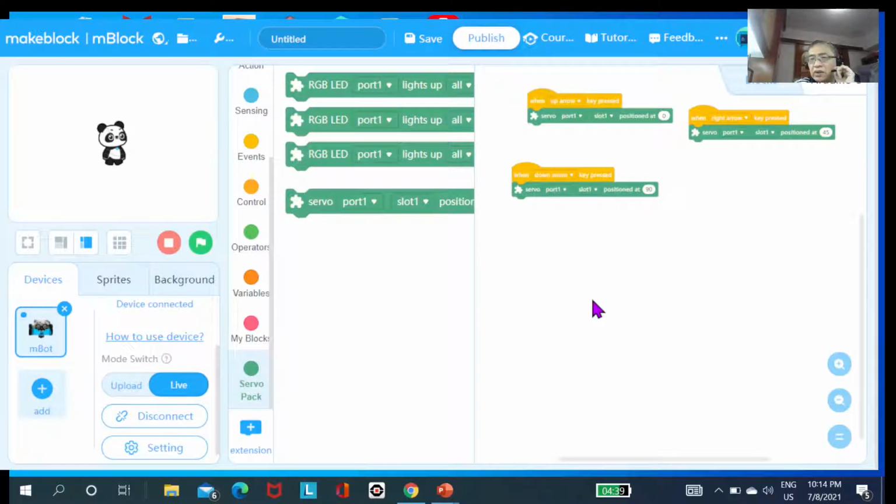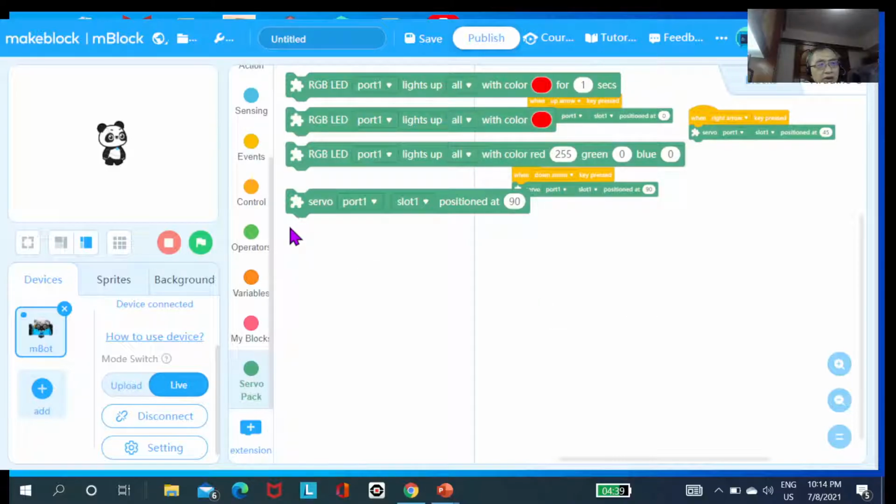In this simple exercise I want the condition that if an object is close to the ultrasonic sensor, less than 30 mm, the servo will turn to an angle of 45 degrees. If that condition is met, it will turn to 45, else it will return to 0 degrees. Let's put together the code to do this.